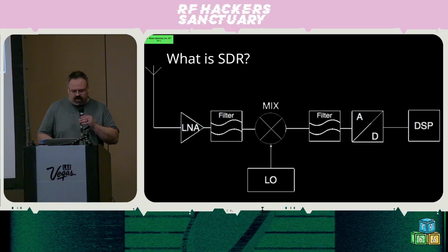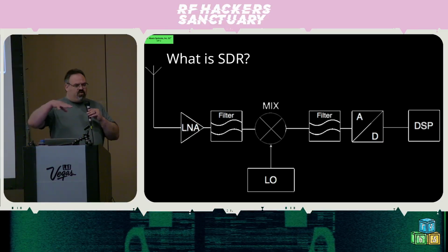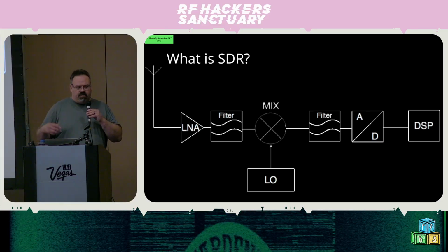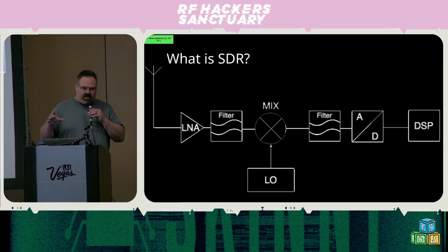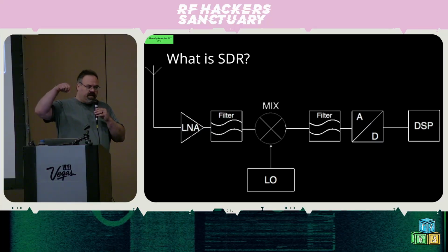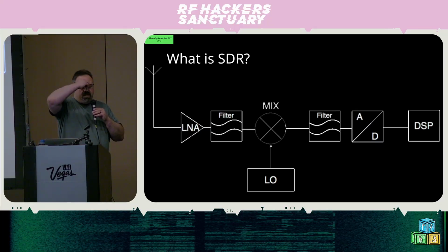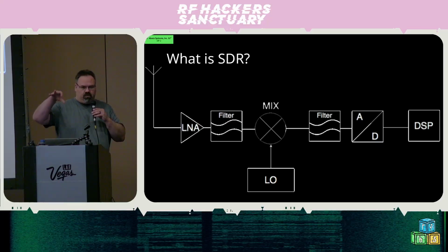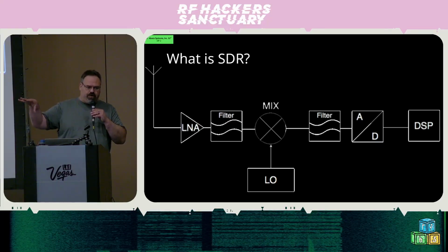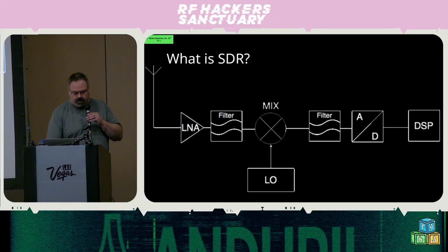Cool. So that's how you end up tuning your radio, is use that local oscillator to feed in to the mixer, to get the output that you want that will actually match up with your analog to digital converter.